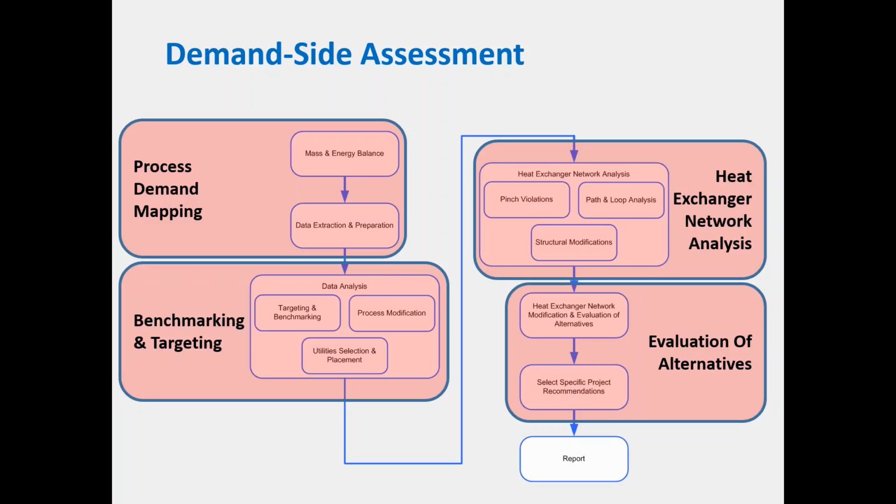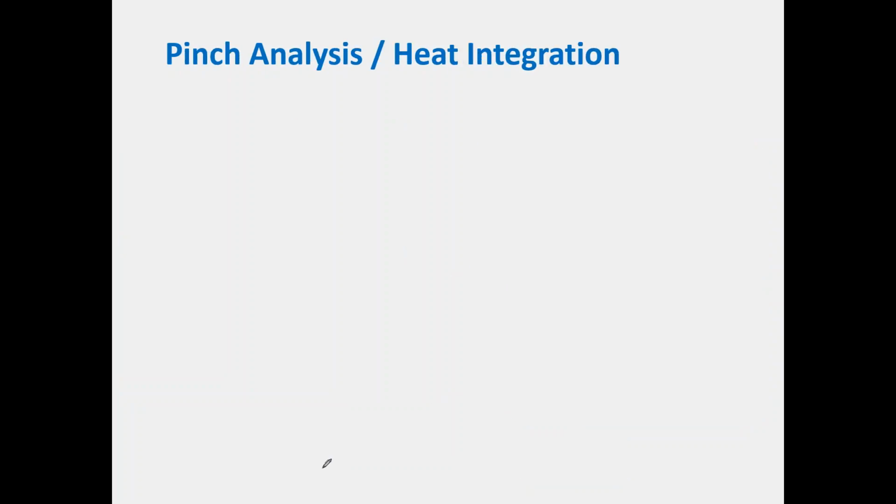And so really the center of this demand side assessment is one of the main techniques to perform this analysis, what we call pinch analysis. We've talked about this in the past, a few years ago in our previous webinars, and we're not going to go into the details today, but pinch analysis or heat integration is a well-established method that looks at how you reduce your utility demand in an industrial process.